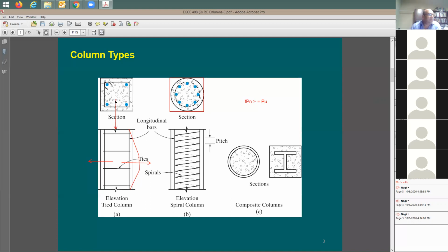So once you start to apply here a vertical load, this column wants to open up. And all of a sudden, if you don't have any of these ties, you're going to see a vertical crack, right? Now, what is bringing the rebars together and putting all of this concrete together is the ties. This is why in column design, the code requires certain spacing of the ties and certain size of the tie itself. So you cannot just go with any tie spacing and any tie size. You need to satisfy certain requirements.